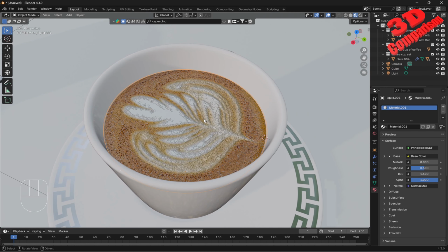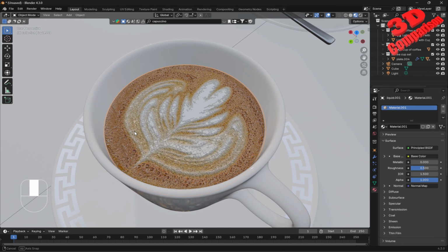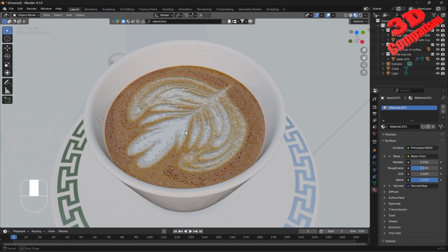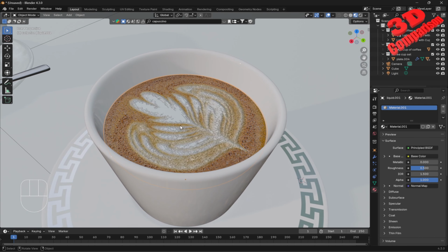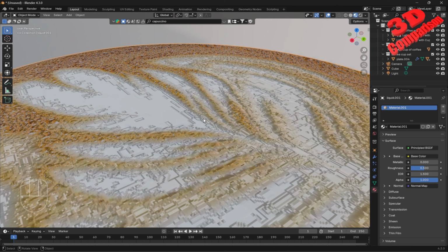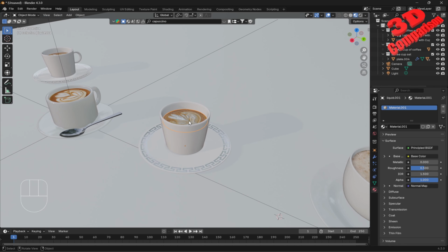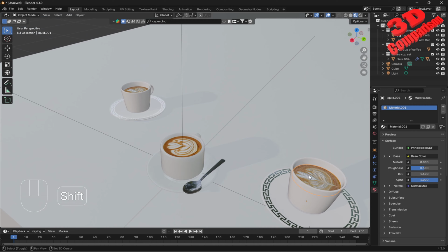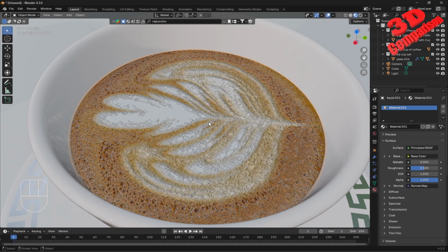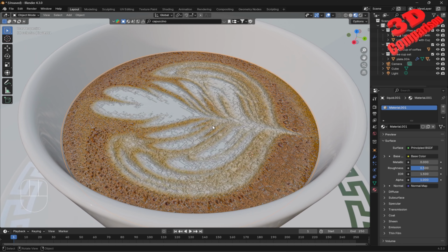If I jump to layout, we're going to see how this will be positioned. Regarding the overlap of the texture, that's really good, but we have the following problem. Since the displacement map worked like this, with the default settings, it added additional gray areas. This is quite similar to the one from the start of the video, which also had the same problems. But we can tune down that amount.